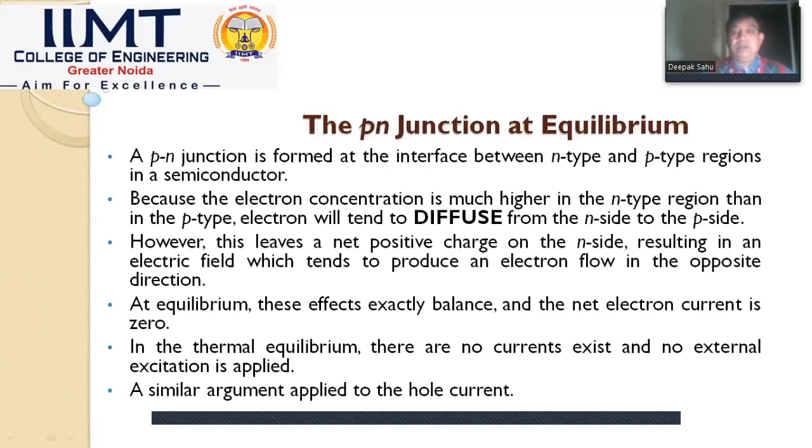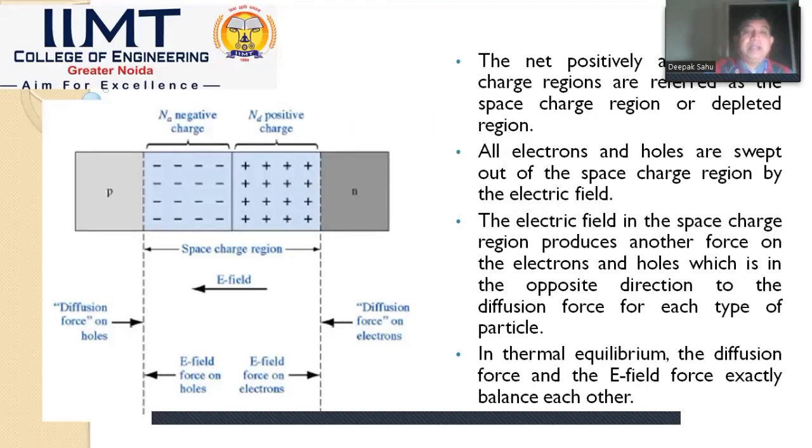Now, the no bias condition is basically a reference, shown as the PN junction at equilibrium. As we have earlier seen, due to the creation of the electric field, whatever charges were moving due to their doping concentration, once a space charge region or depletion width is formed, this movement totally stops.